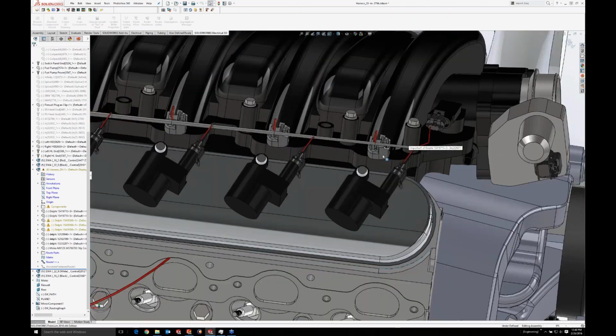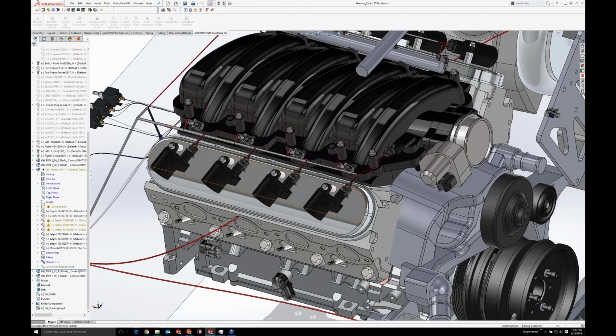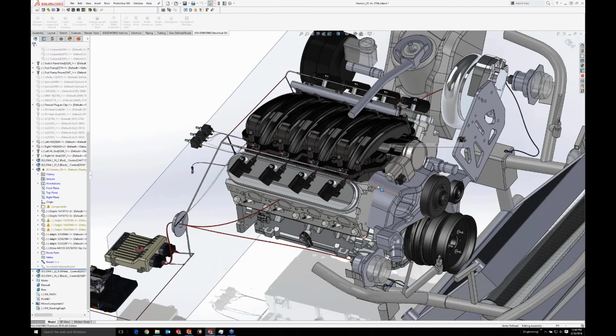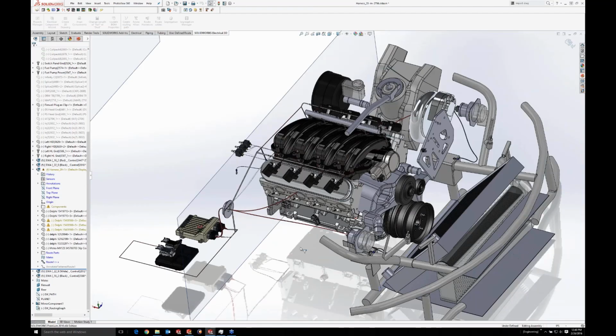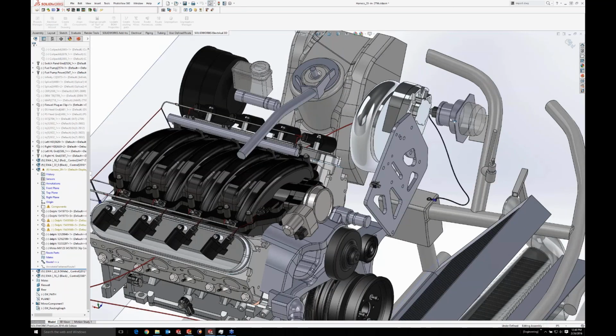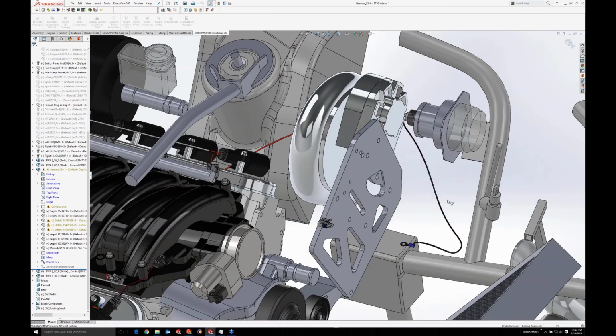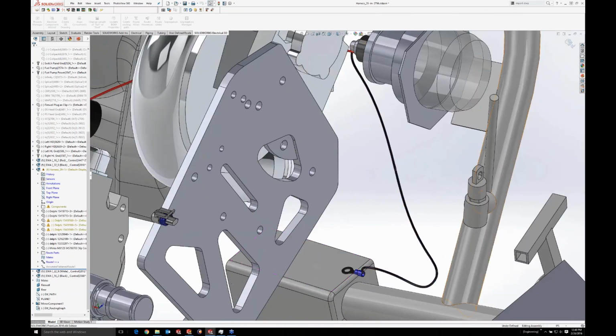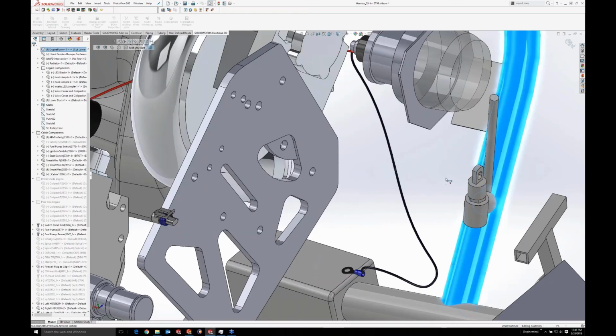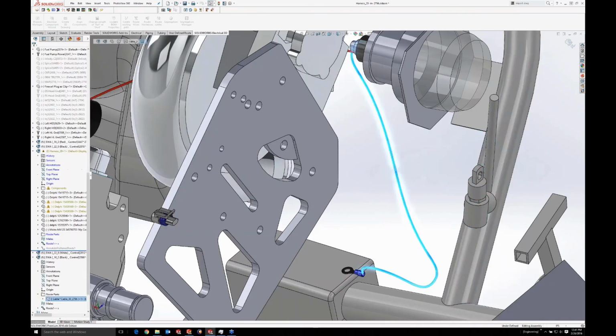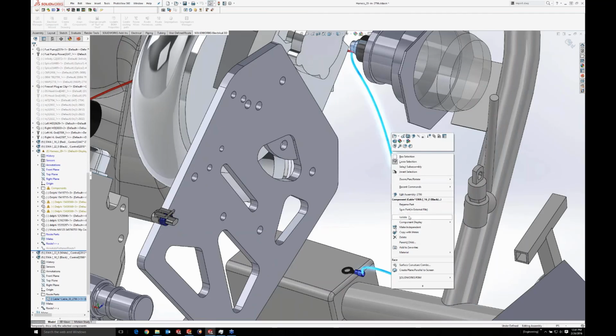All I had to do was mate these connectors where they needed to go. And you don't even really need the assembly to do that. A lot of people say, well, I have a kind of a pegboard of how this needs to go. Okay, great. Mate it like your pegboard, and then hit route, and it'll route automatically. And the automatic route is pretty good. So there might be some tweaking that you need to do. Hey, your spline radius was too small, or hey, this black wire really needs to get zip tied up here to this pole. So edit this route. Well, you actually go click it in 3D and say edit route.